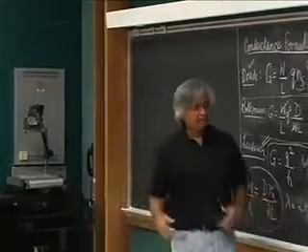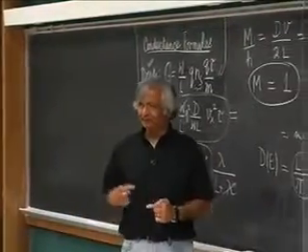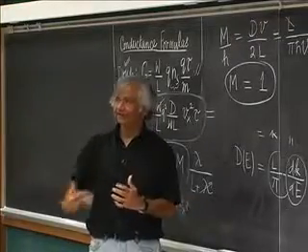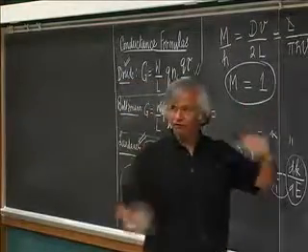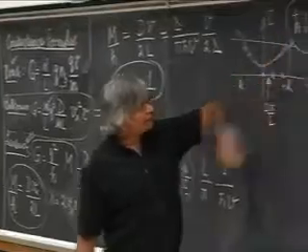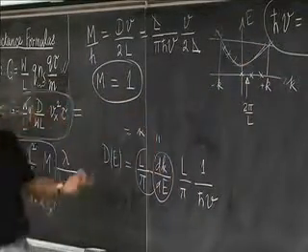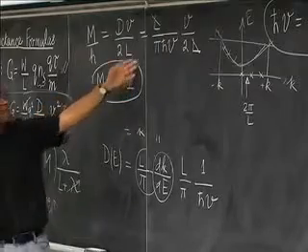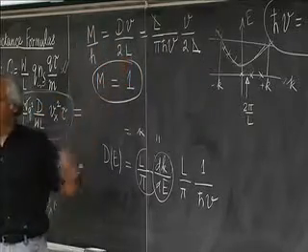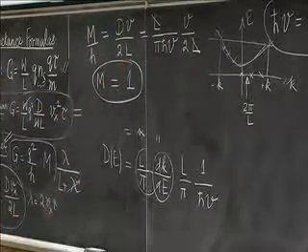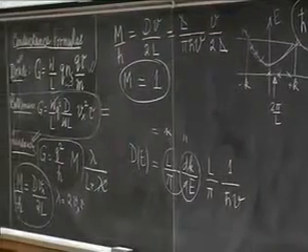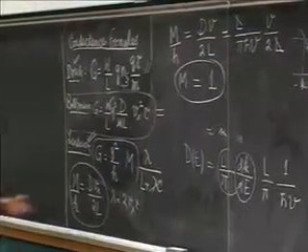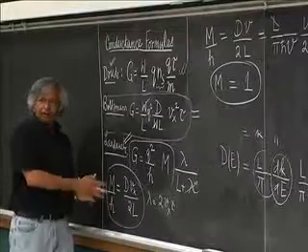But now, of course, we have brought in the E-k relationship, which builds into it the quantum viewpoint, the wave viewpoint, etc. And once you bring that in, then you can see this M, for a 1D conductor, basically becomes 1. It's as if it's a single mode. See? And so that gives this concept, this mode, a lot more importance and significance.